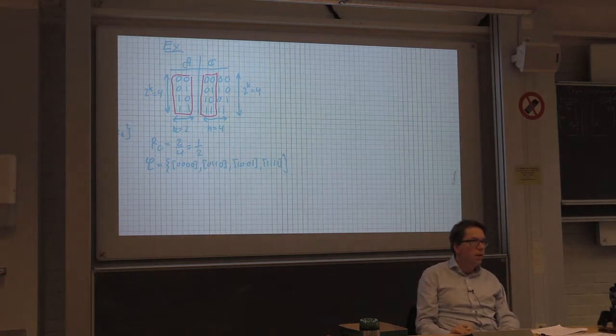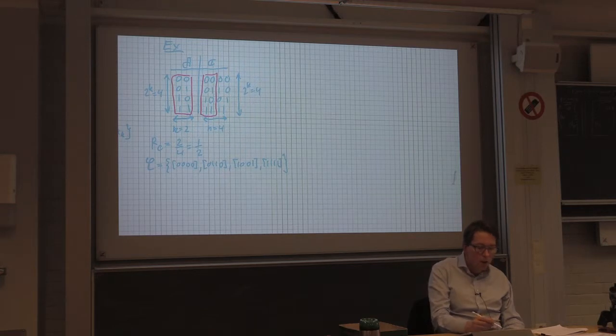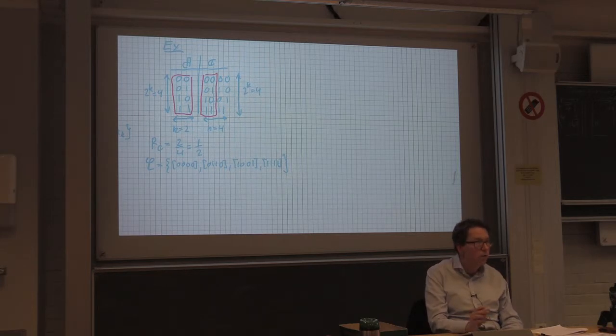So it's a systematic block code. The other bits, the parity bits here, if we look closely at them, are simply the input bits in reversed order. Okay, so it's not a very good code, right? But it's just the way it's done here. Typically, this is a more complicated function of the input bits. We'll see an example later on in this lecture.